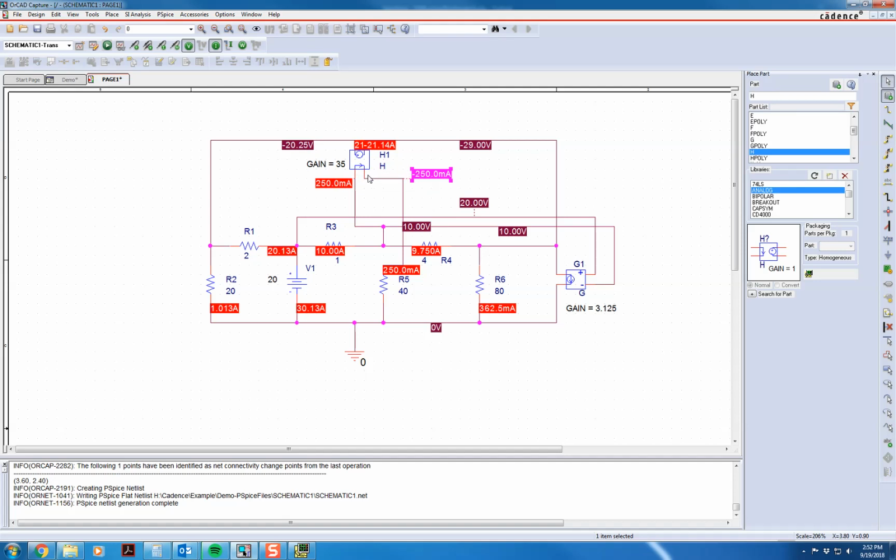I can't find a good spot to put that one, but we can see all of the current, and then of course we could turn power on to see the power dissipated and generated in the circuit, and that this dependent power supply up here has a positive 185 watts, which means it's absorbing power. Dependent power supplies could be absorbing power, always delivering